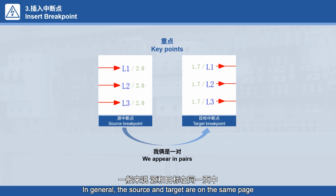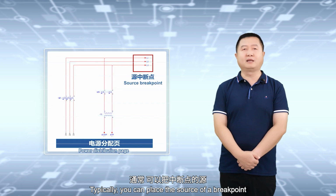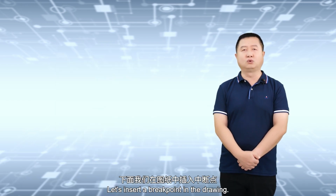In general, if the source and target are on the same page, there is no need to use breakpoints. Generally, breakpoints are used across pages. Typically, you can place the source of a breakpoint in the right half of the drawing page, and the target breakpoint in the left half of subsequent drawings. Let's insert a breakpoint in the drawing.